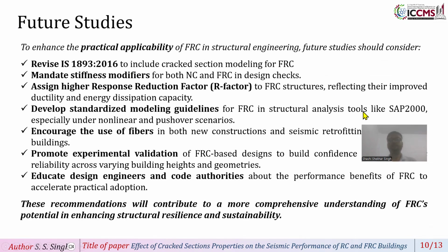These are the future studies. To enhance the practical applicability of FRC in structural engineering, future studies should consider revising the Indian seismic design code to include cracked section modeling for FRC, mandate stiffness modifiers for both normal concrete and FRC design checks, and assign a higher response factor for FRC structures, reflecting their improved ductility and energy dissipation capacity.